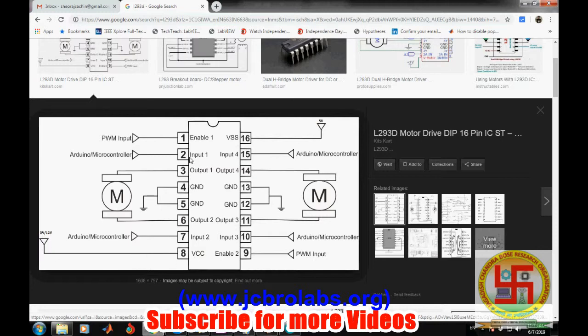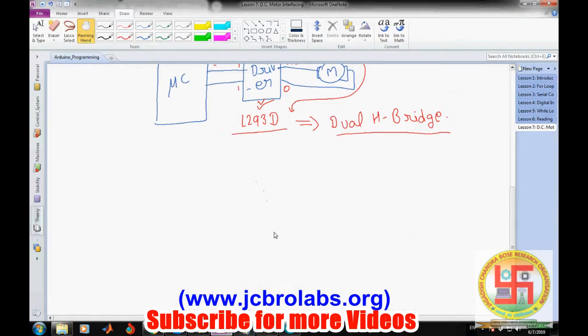Now pin number 2 and pin number 7 are connected to the Arduino, from where we send the command. Suppose we send 1 here, 1 will appear here. If we send 0 here, 0 will appear up here. Pins 3 and 6 are connected to the motor, and the same applies in the opposite direction. Pin number 15 and 10 are connected to the Arduino or any microcontroller. 14 and 11 are connected to the second motor. And pins 4, 5, 13 and 12 are connected to the ground. So let's create a structure here. Okay, so this is how we connect this L293D.